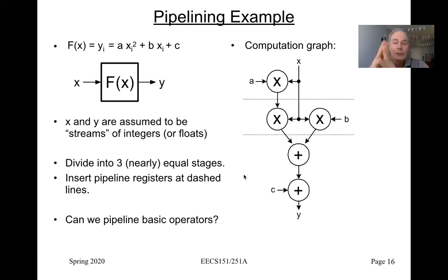Now, simple, we want to think about pipelining this. Well, we can just kind of cut it into stages, sort of like what we did with the processor. And you want to think about how to cut it to get somewhat balanced stages. We'll see later, but multiply is significantly more complicated than add. So sort of arbitrarily here, I just decided I'm going to put these two adders in one pipeline stage and then put a pipeline stage with those two multipliers in parallel, and then this multiplier in its own pipeline stage. So this would be a three-stage pipeline.